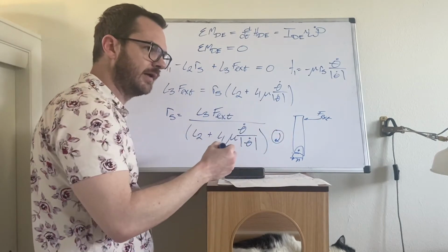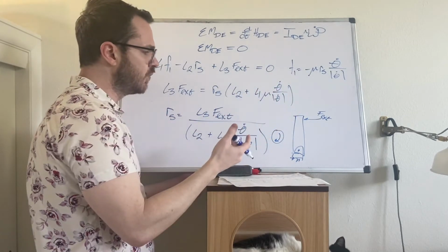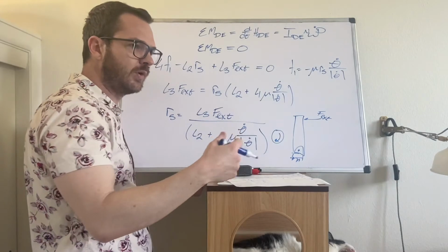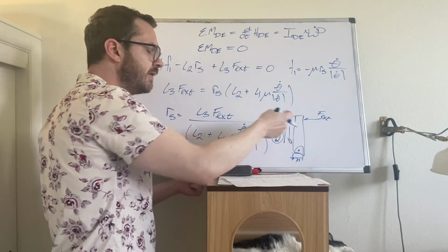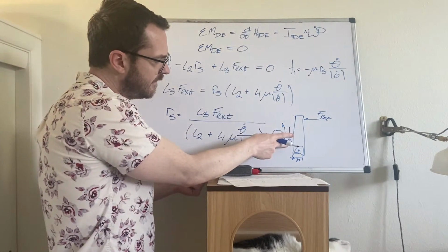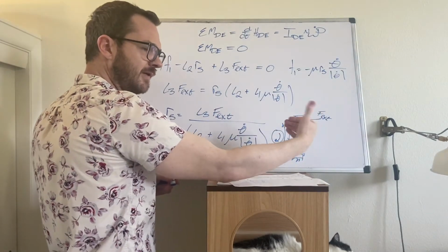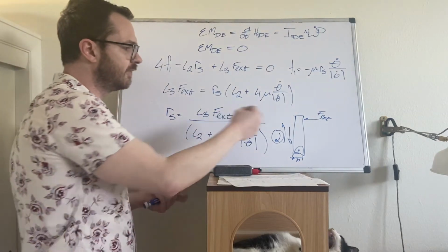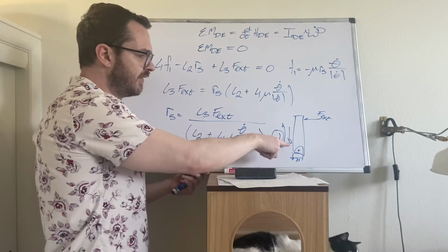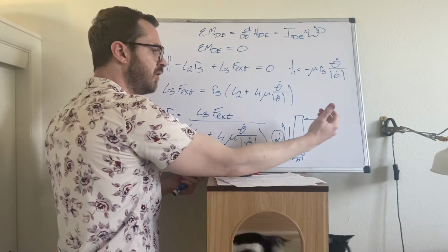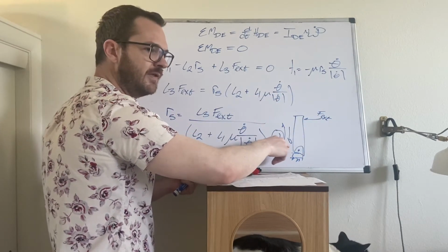Now the disk is rotating in this direction. Well, if the disk is rotating in this direction, a negative spin, then the friction at the surface is going to be positive because it opposes the motion, which puts the friction on the pendulum negative, and we can see that force pointing down on the left surface would create a positive moment on the pendulum. That positive moment on the pendulum, it's small, right? It's a function of just these widths, but that little bit of friction right there would actually pull the handbrake onto the disk, and it's actually going to increase the reaction between these two.